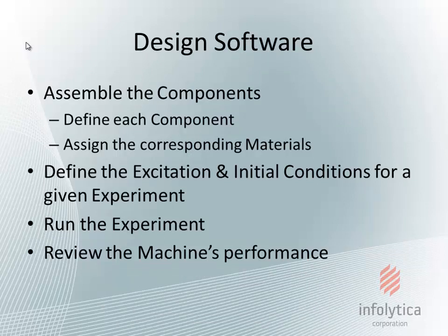MotorSolve is a design software. It has specific interfaces which allow you to assemble the components. You define each component, you assign them materials, and then you define the excitation and the initial conditions for any given experiment. Once the experiment is set up, you run it, and then you review the machine's performance.